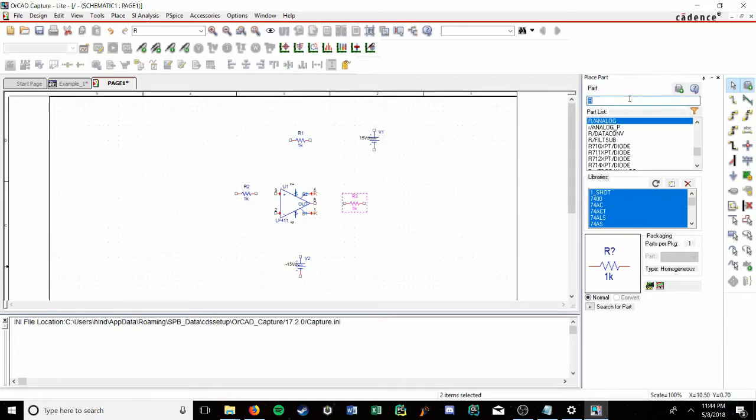Lastly, we'll need a capacitor for our passive elements. Again, see this capacitor here, you don't want to use it because it's got the PWL comps. I just type in C by itself and you get the C analog. We'll need one of those below your resistor, or above, it doesn't matter, they're in parallel.